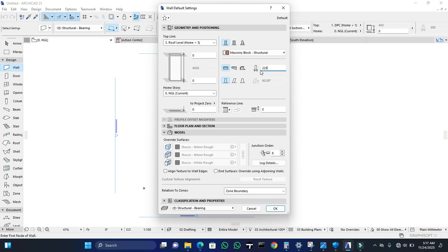So you can set the block thickness to 150 or 225, but for a bungalow basically we use 150 millimeters thickness, because we are working with the metric system. If you convert those units to imperial, that's 6 inch blocks, and 225 is 9 inch blocks. I hope you understand. So 150 millimeters, that's okay. Now this is good.